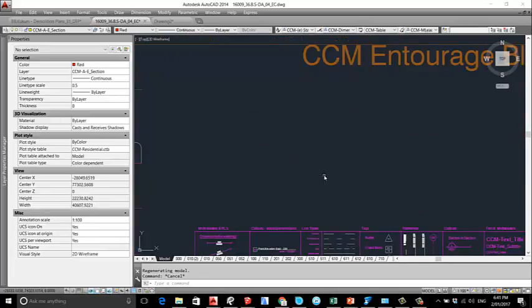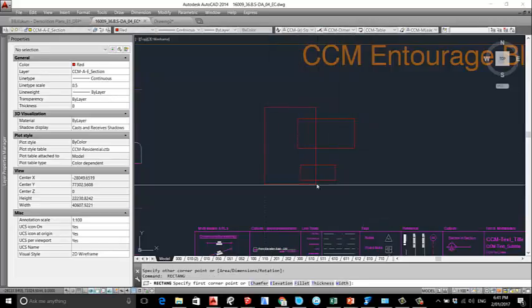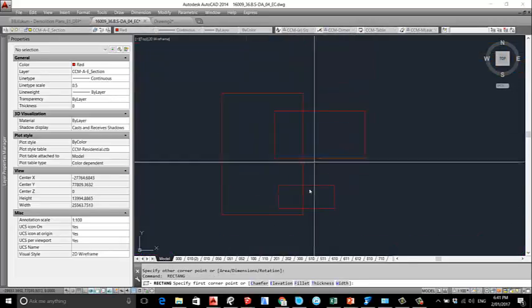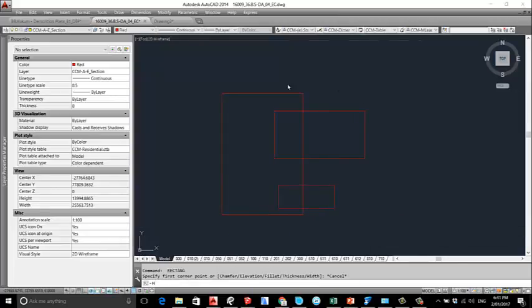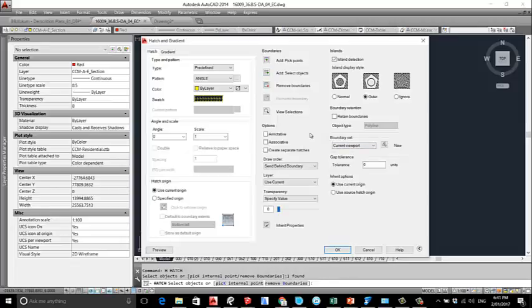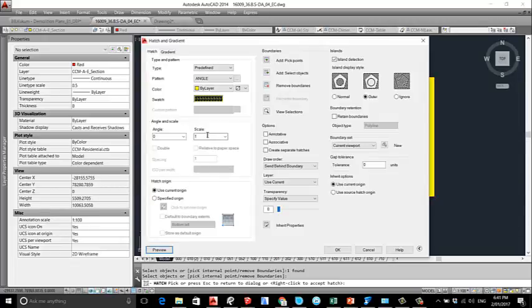Hatch might not make sense in some cases, it might make sense in some other cases. So let's see, what do we do? Let's do something like that. So this will be our block of whatever this shape is, we don't know. And let's do hatch in here. That is this one. Let's see if the scale is right. It's a bit too small. Let's do 20. Okay, that's okay. And we can say that it's annotative, in fact.